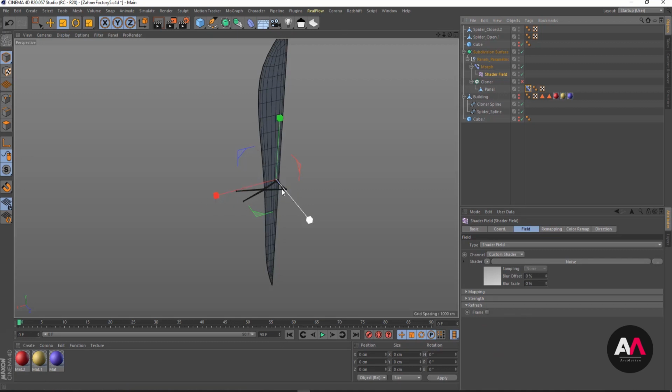If the spiders are not positioned in the right position, then the spider's condition can vary at the end, and it may not be compatible with the panels and with the form of the panels. That's of course a thing that we don't want. So it's really important to have them in the correct position.